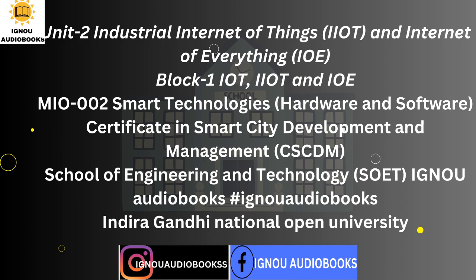Plants are deploying more sensors for equipment condition monitoring to improve reliability and reduce maintenance cost, for performance monitoring and loss detection to improve energy efficiency, to automate manual data collection for productivity, and to meet ever more demanding safety, health, and environmental (HSE) requirements. For instance, a very fast pressure transmitter with embedded statistical process monitoring (SPM) can detect pump cavitation to notify operators to check for closed valves, and maintenance to check for plugged strainers.